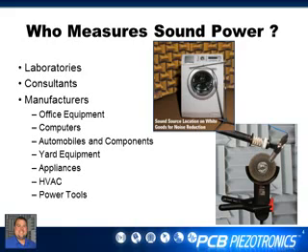And actually, many manufacturers around the world perform sound power measurements on office equipment, computers. You would think computers are pretty quiet already, but once you have a large group of computers, it becomes additive. It's just like everything else. It's superposition of sound. As you increase the number of sources, the overall sound power level increases with the sum of the sources. Automobiles and components, yard equipment, so lawnmowers, tractors, weed whackers, they're all on the list of things that are tested for sound power.